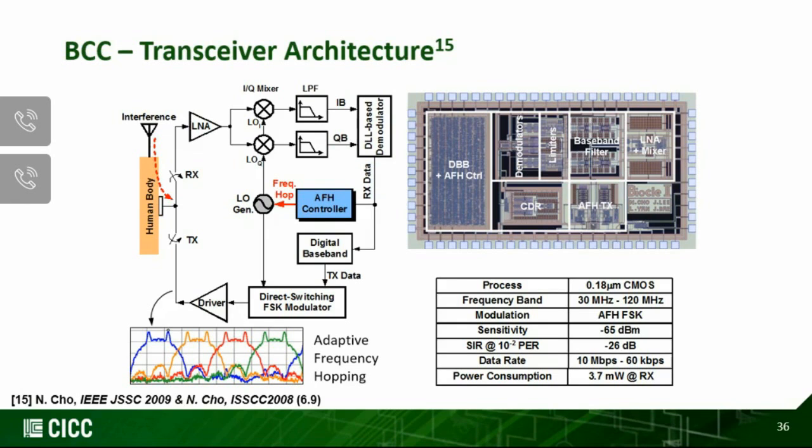However, the transceiver shown uses direct switching FSK instead, with two dedicated separate PLLs. At first glance, the TX seems to consume much more power than conventional FSK modulators, as it has two separate PLLs. But that is compensated by not adopting up-conversion mixers and using a low carrier frequency, as most of the PLL blocks are simple digital logic. As a result, using the direct scheme will result in less joule per bit.